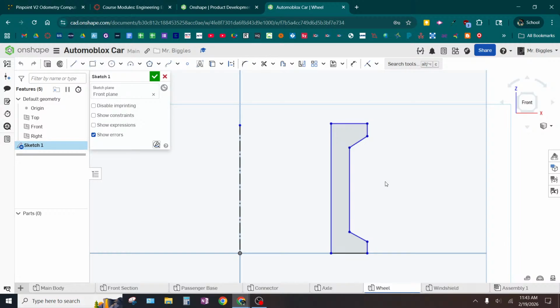I am going to tell you right now that if, just drawing this, you accidentally apply constraints you don't want, you're probably better off just restarting from scratch. Delete it, restart. If you don't apply constraints that you want, that is a much easier thing to fix. You could just apply them manually. So if you didn't draw a certain line and get the snap to constraint, for whatever reason, you just have to apply the constraint later. But if there are extra constraints in what you want, unless you really know what you're doing, it's tough to find those. Okay? Do you have questions?